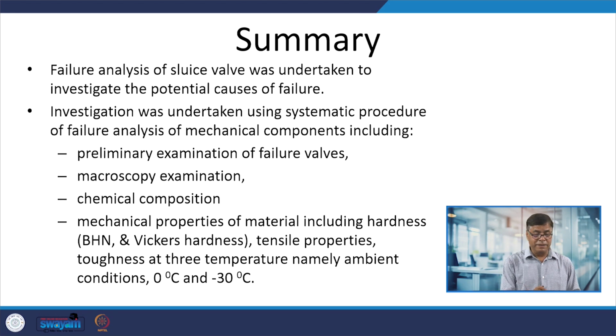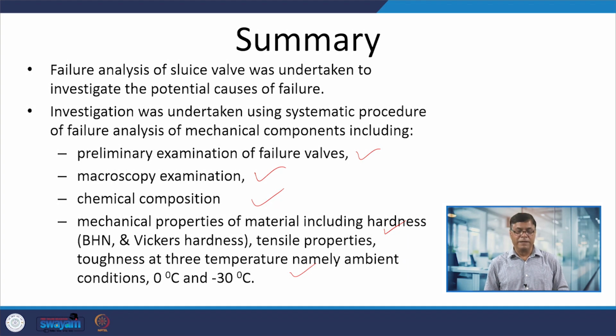The summary here is that the failure analysis of the sluice valve was undertaken to investigate the potential causes of failure, using the systematic procedure of failure analysis of components. We conducted the preliminary examination of the failed component, microscopic examination, chemical analysis, and mechanical properties, in order to come to conclusions about which factor predominantly contributed towards the failure.